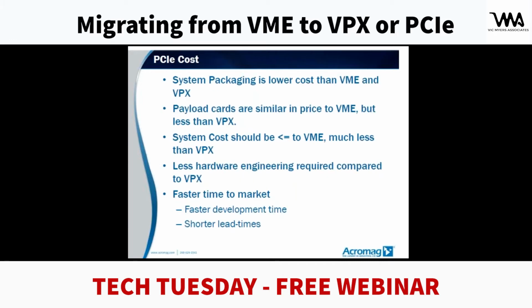The cost of PCI Express server architecture is typically, from a system packaging standpoint, lower than VME and significantly lower than VPX. Payload cards are very similar in price to VME, but significantly less than VPX, and we'll talk about why that is. So in general, system costs should be less than or equal to VME and much less than VPX.